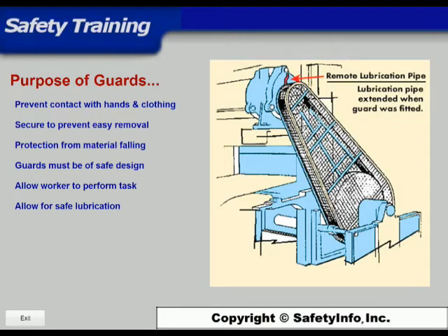So far, we've learned that machine guards provide a barrier between you and the dangerous parts of a machine. However, there are some very specific guidelines for machine guards. First, machine guards must prevent hands, arms, or any body clothing from making contact with dangerous moving parts. A good safeguarding system eliminates the possibility of the operator or other workers placing parts of their body near hazardous moving parts.